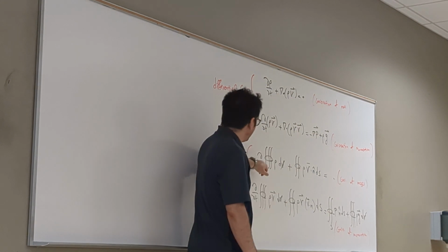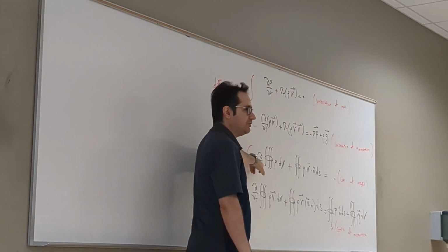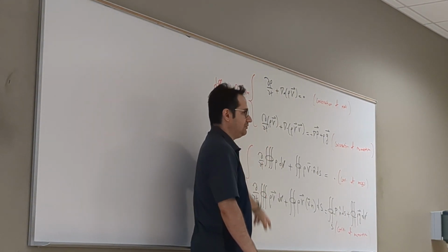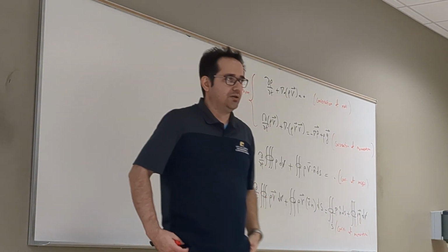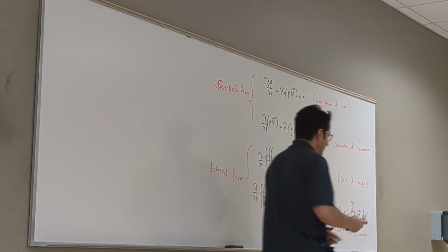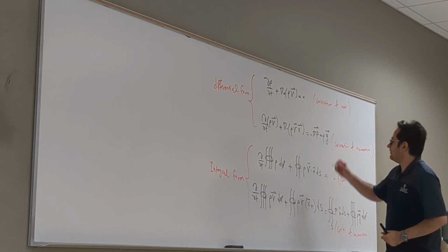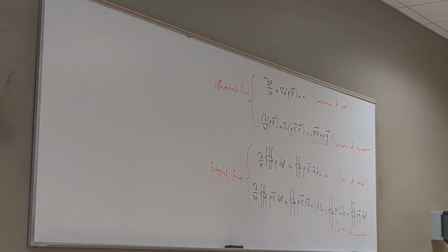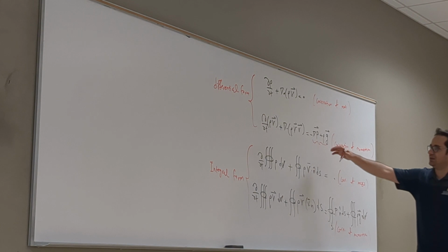Now, the first one of these is continuity, or conservation of mass. The second one is momentum, or Newton's second law, conservation of momentum. This is very important: the right-hand side is the summation of external forces from Newton's laws, and those viscous terms will be ignored. We intentionally ignored the viscous effect, and we said if you ignore that, then you get inviscid.